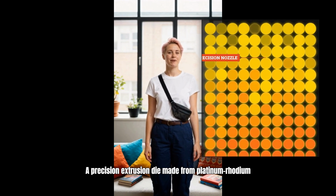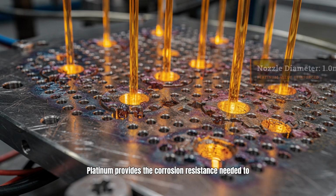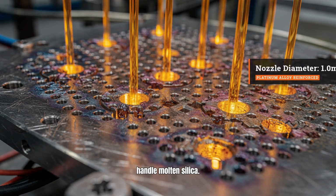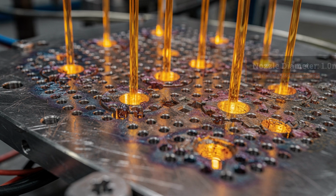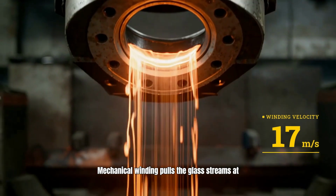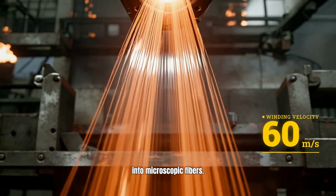This is the bushing, a precision extrusion die made from platinum-rhodium alloy to survive the extreme heat. Platinum provides the corrosion resistance needed to handle molten silica. Each hole creates a single, continuous filament. Mechanical winding pulls the glass streams at high speed, thinning them from liquid blobs into microscopic fibers.